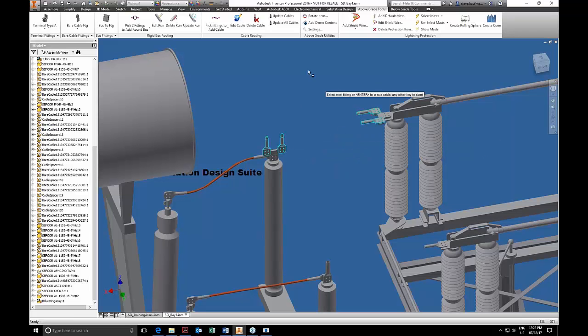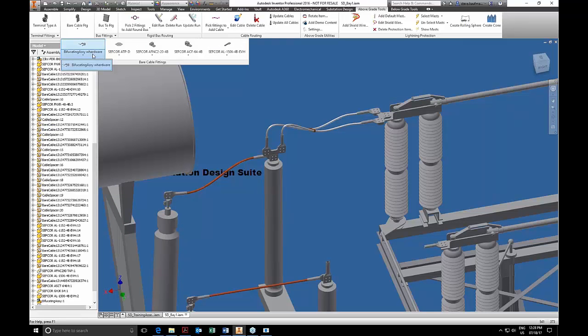P for pair. And away we put that in. So it's really nice that we can put in assemblies. What I'm showing you, I can put that assembly in its own group. I could have a whole bunch of assemblies in here. One thing to note, though, all the items that are in this assembly also have to be in the bill of material.